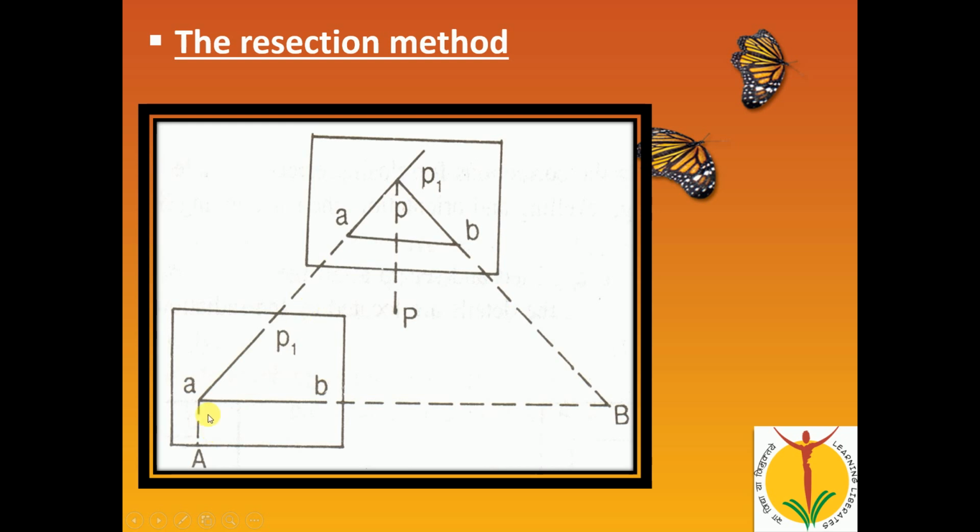And if you have chosen some point here, with the help of tape we are going to measure the distance, and we are going to mark the position of point P1. After this we are going to shift the plane table exactly over the station P1, and we have to do the back sighting.